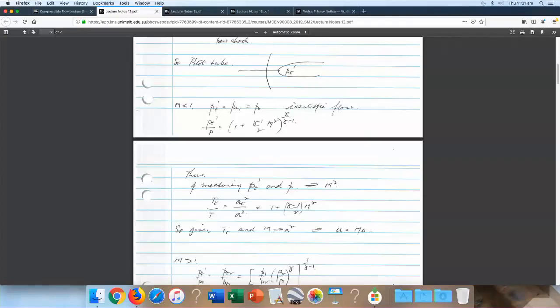So is that shock created just from the pitot tube? Yes. So does that mean that the pressure that's measured from the pitot tube is effectively not completely accurate? I know it's accurate. It is the total pressure behind the normal shock. So that's a good point. It's the total pressure behind the normal shock. So it's PT prime. It's the total pressure behind this shock wave. And it's on the axis. So it's accurate.